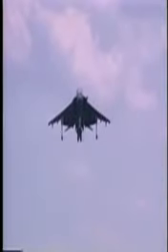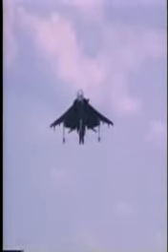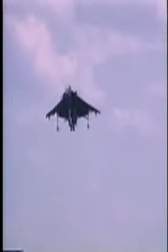Another type of airspace is called other airspace areas. An example of two types of airspace in this classification are military training routes and airport advisory areas. Both IFR and VFR military training routes are depicted on sectional and government en route charts. Flight operations along these routes are typically flown below 10,000 feet MSL at speeds in excess of 250 knots.